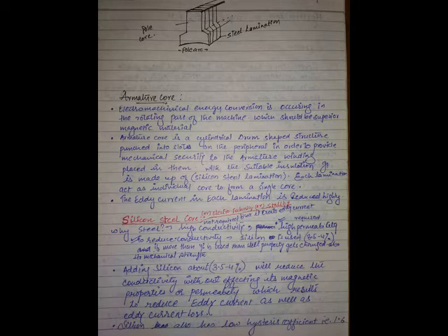But when the potential increases, it will automatically conduct through the air as a spark and the current will enter. Sparking means current flowing through air. Now, if a small air gap exists between the commutator and brush, what happens? If a thin air gap exists, the current definitely flows, and since the brushes are collecting current, the collection of current will definitely happen through a spark.